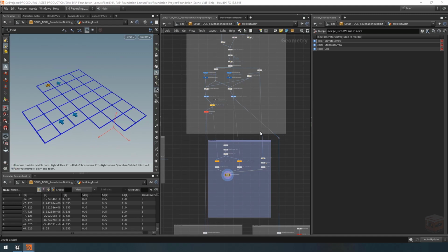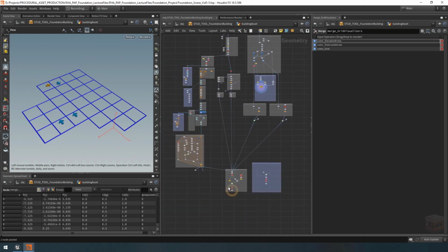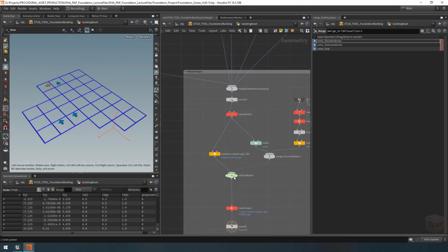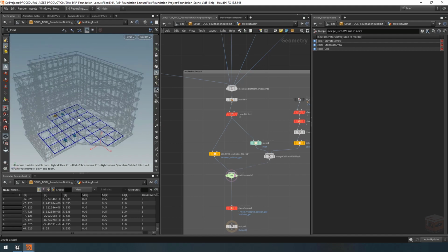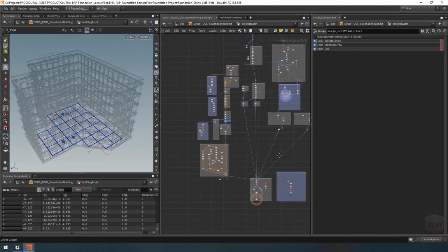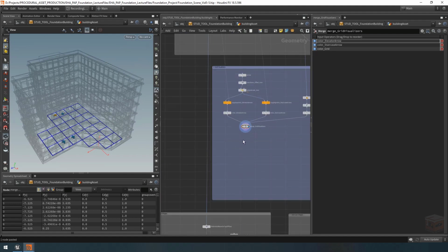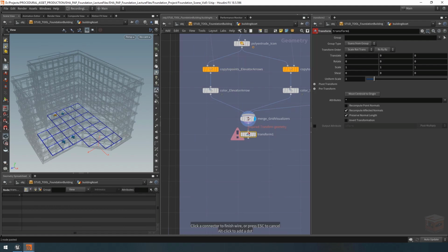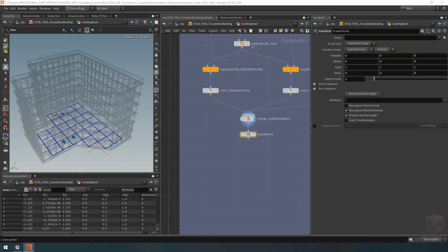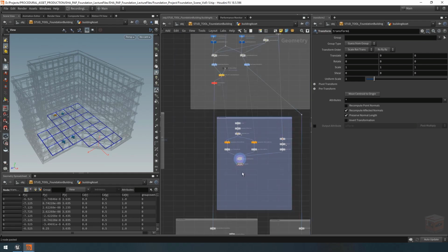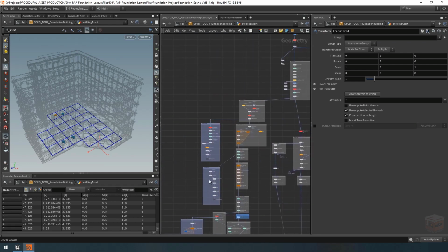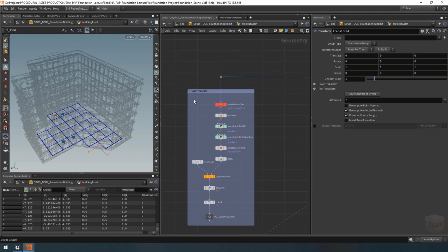Now, at this point, it's still sitting at the bottom of our building. If I template out my building, then it's currently, well, inside the ground, not something we can use. So let's grab a transform node, plug it in here, and let's raise this thing up to the roof. And I would like to grab my current floor count, the current height that we're using, just like how we did here for our seam visualizer.